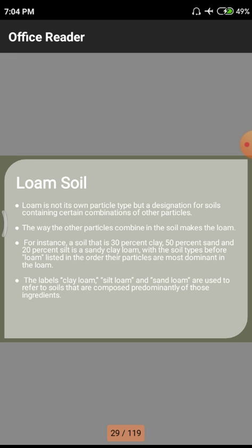So those are directly proportional to the soil bearing capacities of foundations. If the foundation is weak, automatically the total structure will collapse. That collapse means normal cracks will be observed on the structure within 5 to 10 years after the construction. That means in the beam column joints, in the columns themselves, and in the slabs, they are having micro and macro